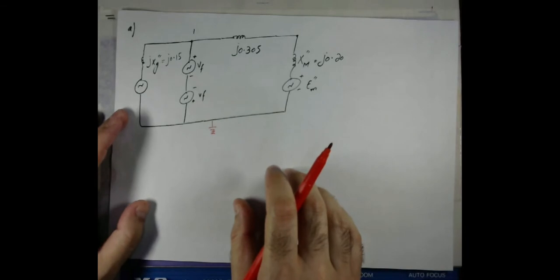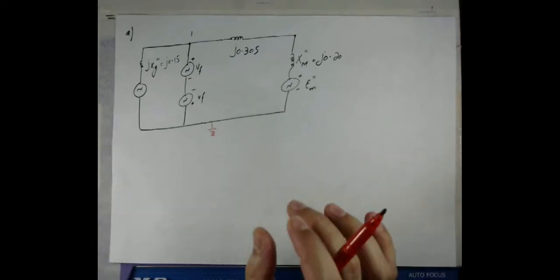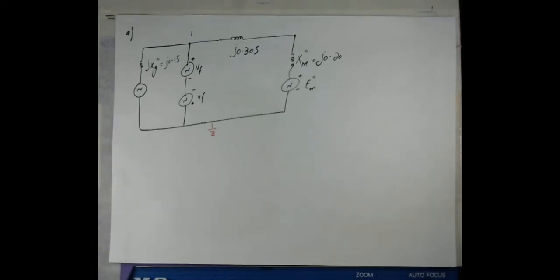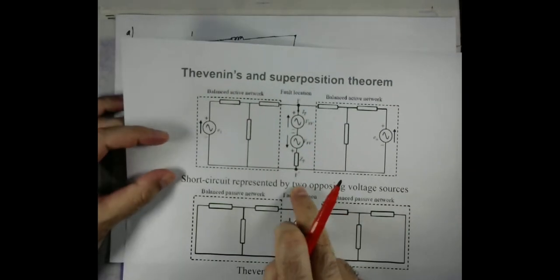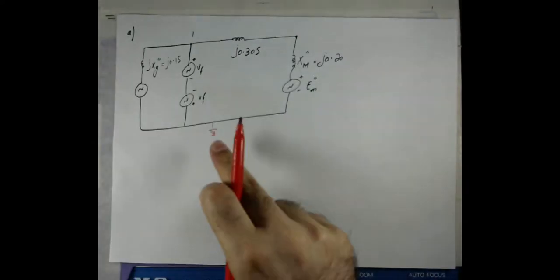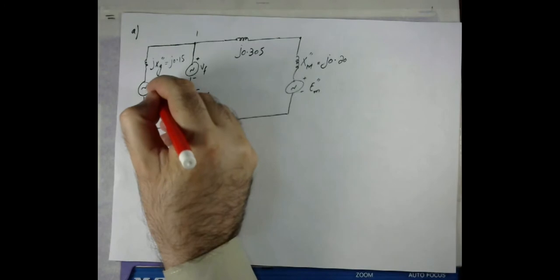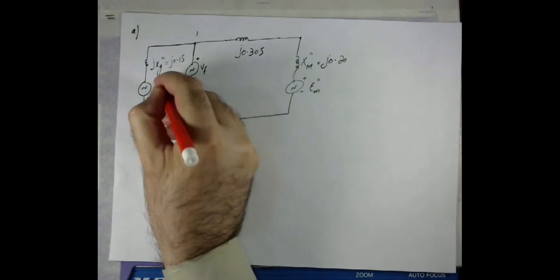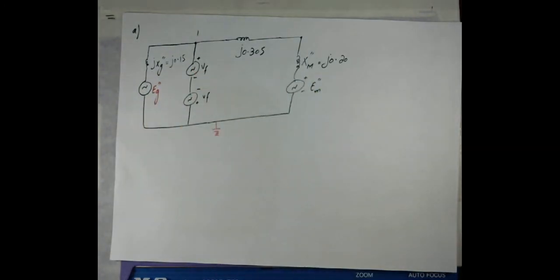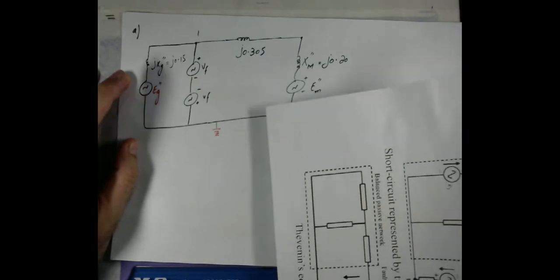Now, as I mentioned, this is the representation of a short circuit type fault at bus number 1, and let me even write here E G double dash, with the double prime meaning the subtransient internal voltage, and that of the motor, and the rest of the parameters in the circuit.